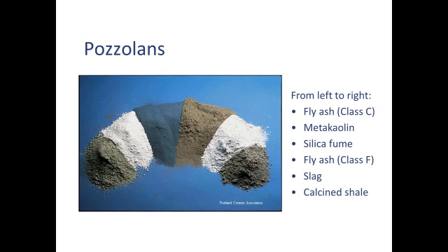Fly ash tends to be sort of a light grayish brown. I've seen fly ash that's almost pale buff. I've also seen fly ash that's almost black, and a lot of the darkness comes from carbon content. Metakaolin is very white. Sometimes it's kind of a creamy pink. After it reacts in the concrete, the color goes away. I've made white concrete with metakaolin that looked kind of pinkish cream, and it looked identical to white cement-based concrete that didn't have any metakaolin in it.